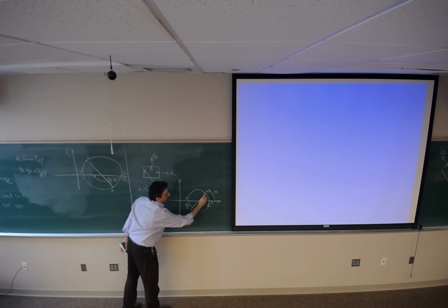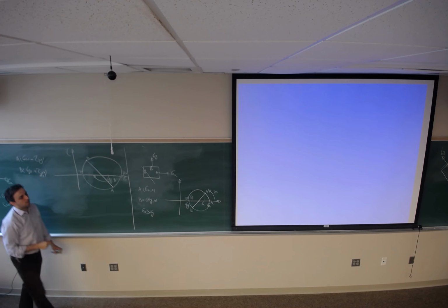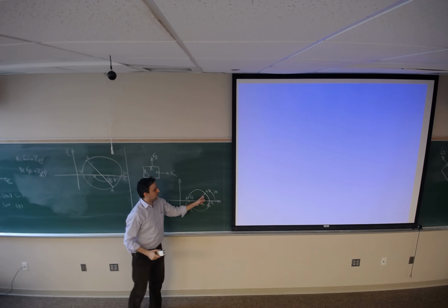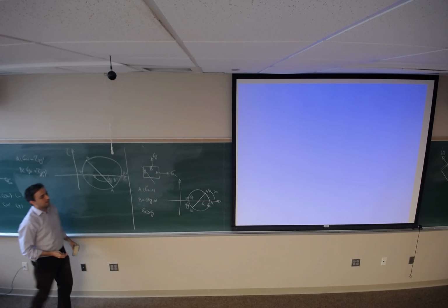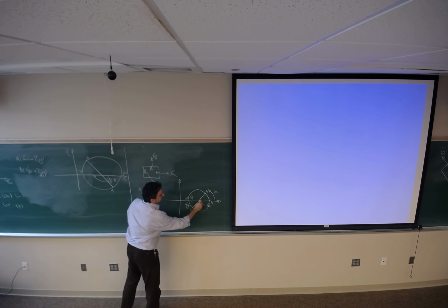We are looking for this as sigma prime x, this as sigma prime y, and this then as tau xy, which are the coordinates of normal and shear stress for point A and point B. So what would be this? It's going to be center plus r times cosine of 2 theta.